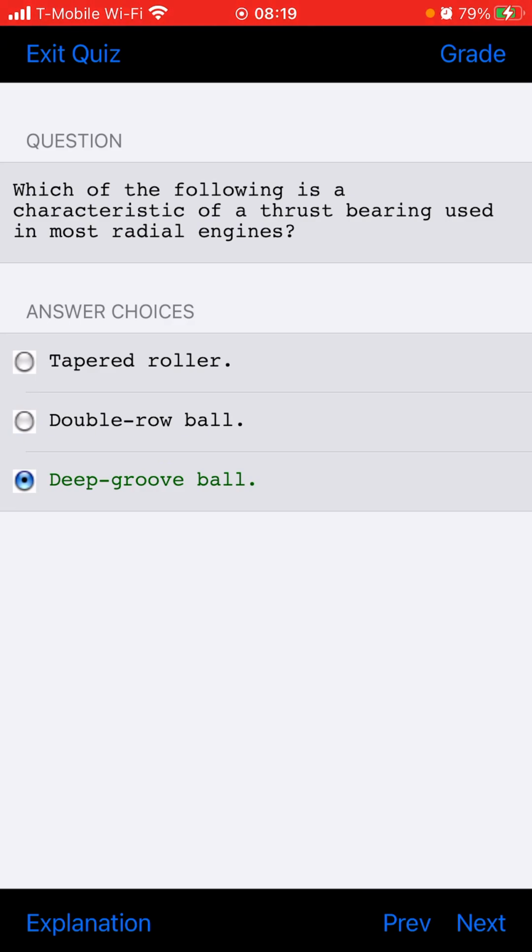What is an indication that the primer is leaking or is open during engine operation? Engine will not idle properly. What are some indications of induction system leakage? Low power and uneven running.